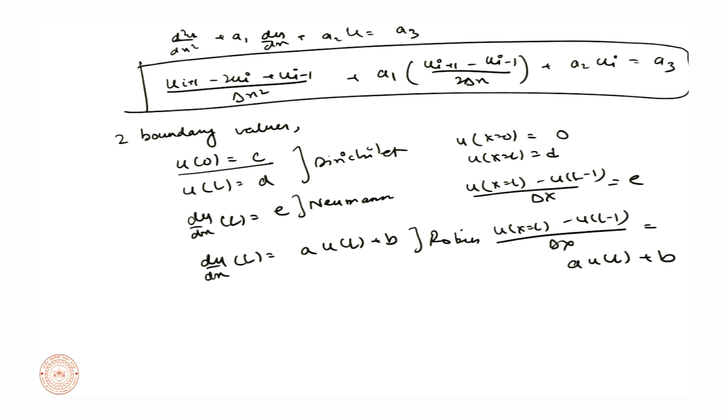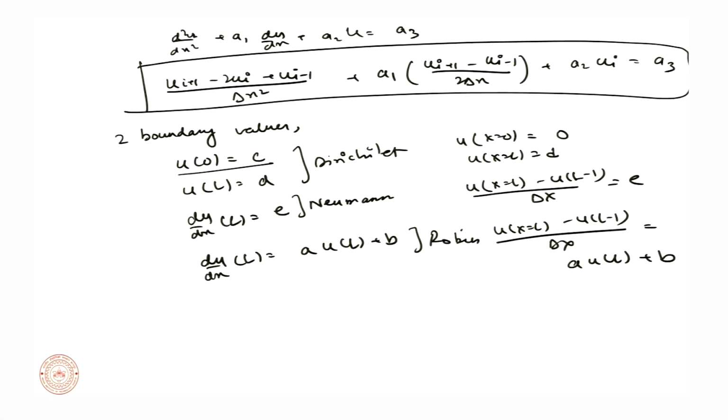Using these, what you can do is you can either do an implicit or an explicit method. In explicit method, you take a set of guess values and then based on those guess values you can solve. In this case, you will have to iterate till convergence. So, you say that you define u as some say zeros or 0.5, then set this expression up. This is what we want to find, u of I is known, this is our interest, this is our unknown. So, the unknown part you take from the guess value, you solve everything based upon the boundary conditions and then you iterate again. So, you have now a new set of guess values, use those guess values to again repeat this iteration till you converge.